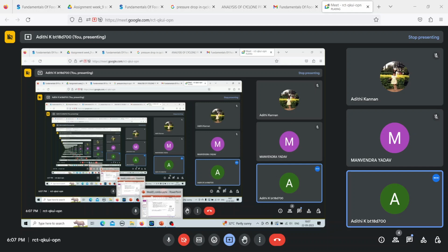As you filter, all your solid particles will get stuck on one side of the filter and form a cake. That cake will also have some resistance to the flow across the membrane. So the cake also gives a certain resistance, which is given by alpha. A is the filter area. Cs is the concentration of the suspended solids that need to be filtered. Delta P is the pressure difference across the media, across the entire process, that includes the cake as well as the filter medium. And Rm is the resistance due to the filter medium alone. So you have two different resistances here.